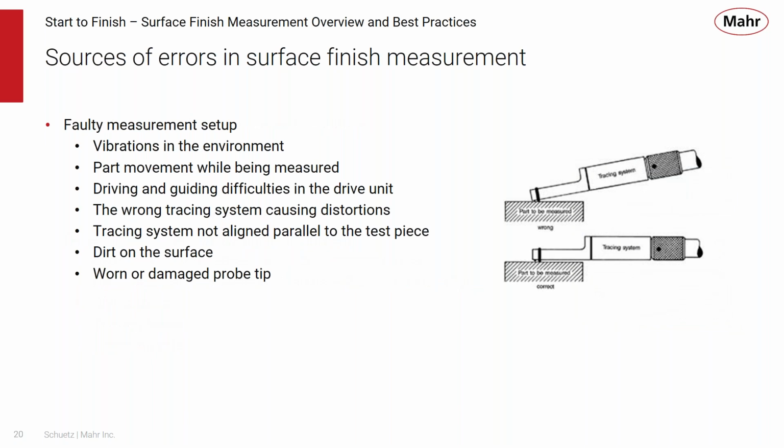In terms of the setup itself, vibration in the environment is going to cause noisy readings or an influence on the results. If a part is moved during the process, that's going to cause an inconsistency within the results. Driving or guiding difficulty: if there's something going wrong with the drive, if it's getting stuck during its process or some grime might have got in there, that can affect the results. The wrong tracing system may cause some distortions in our process.